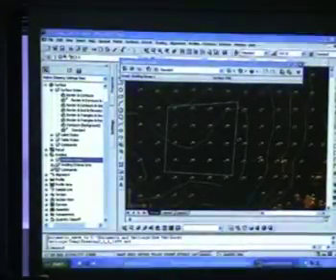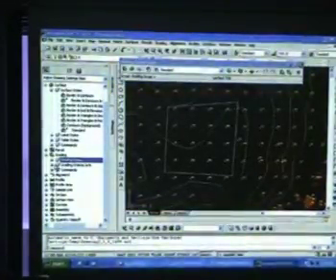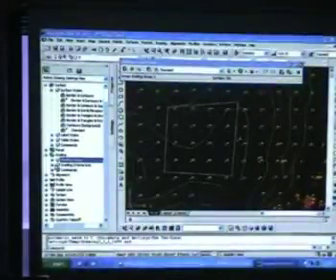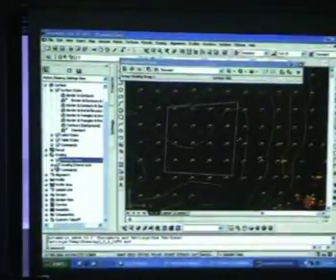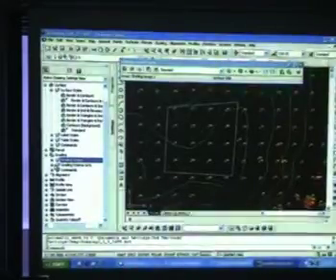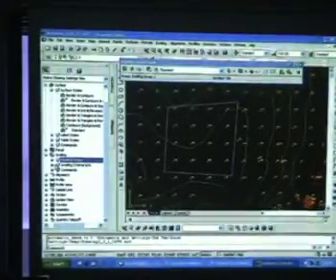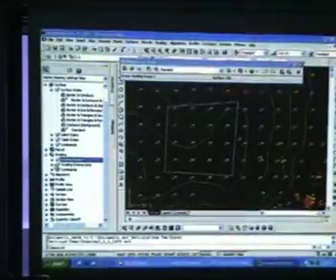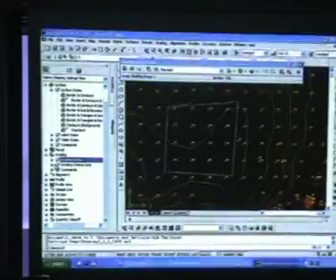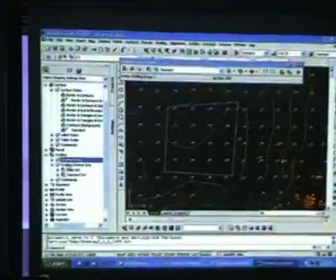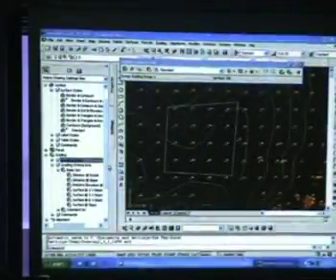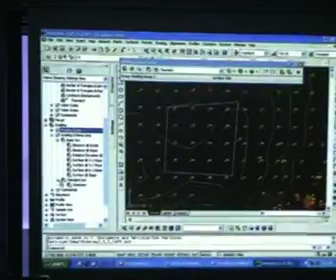Okay? Sometimes, if it's daylight, you want the cut or fill from the platform to go all the way up or down until it finds the original ground level. In some cases, you may want them to go down to a particular set elevation, maybe an absolute elevation of 30, for example, or a relative distance of maybe 1 meter. So this is what the grading criteria set is for. It holds all that kind of information. So these are some of the sets that we have.